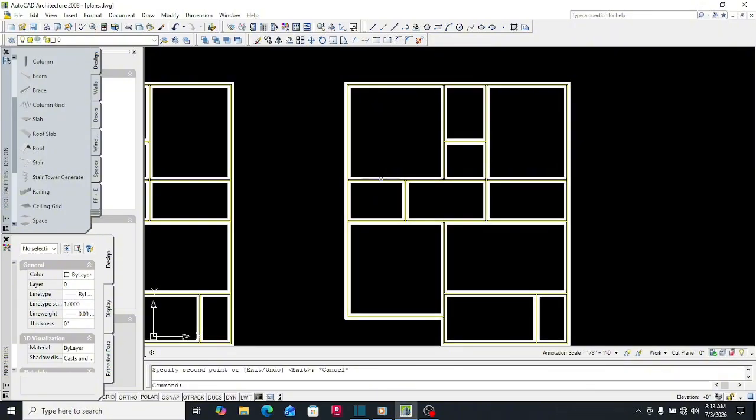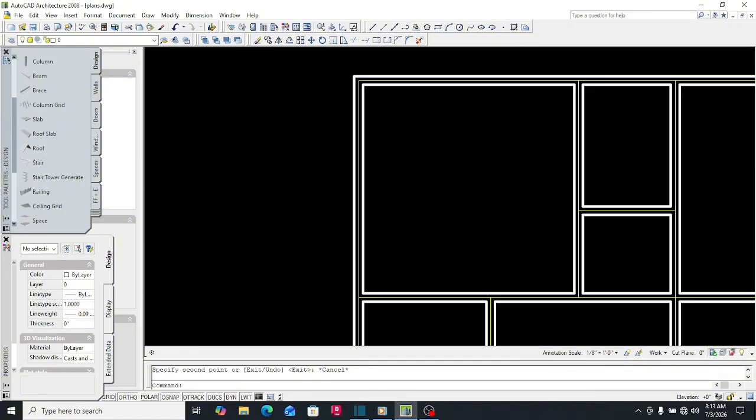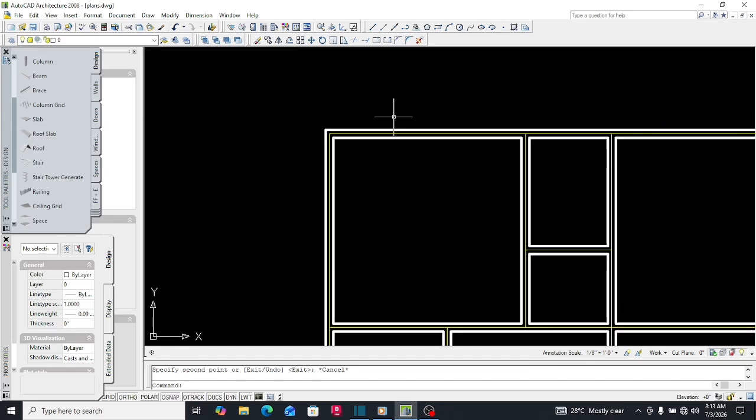Someone will ask, why do we have to extend the width from 6 inches to 18 inches as a trench? The reason is, the trench has to be bigger than the 6 inch block, or the 5 inch or 4 inch, whichever block you are using. The 6 inches beside the blocks creates space, or comfort, for the mason or whoever is going to build the house to fit the block on the foundation bed.